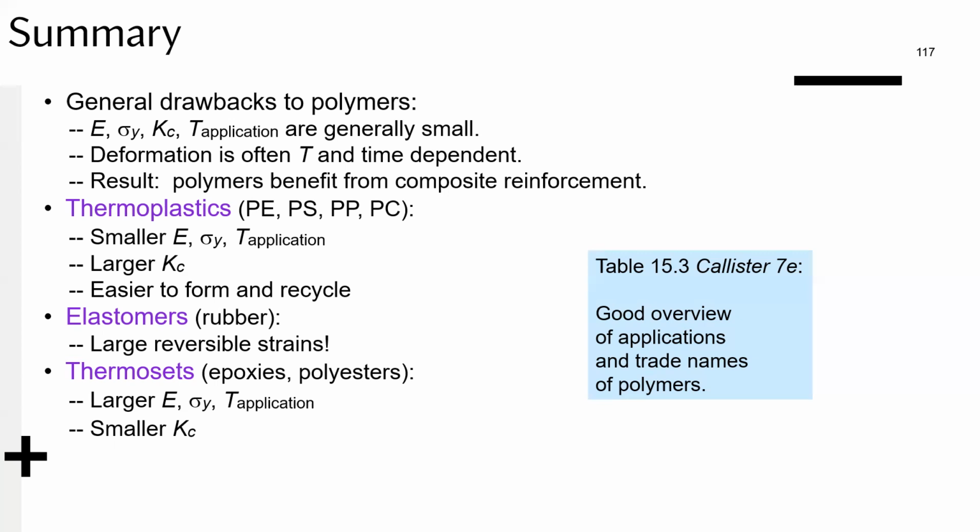And the reason for that is that thermosets, because you use the curing agent and they cure to a very high degree, the cross-linking is really significant, whereas thermoplastics usually have a plasticky behavior and lower degrees of cross-linking typically, whereas thermosets can become really highly cross-linked and stiff because of the nature of the chemical bonding, and that it happens more uniformly and more abundantly.